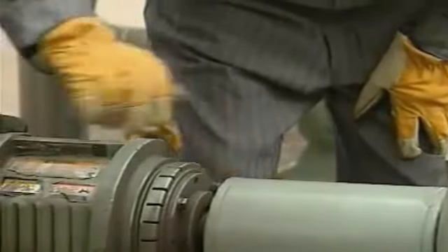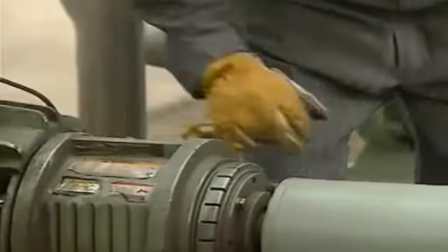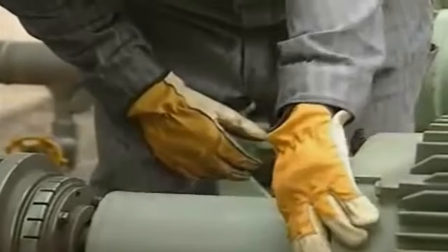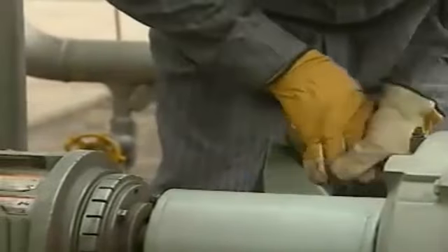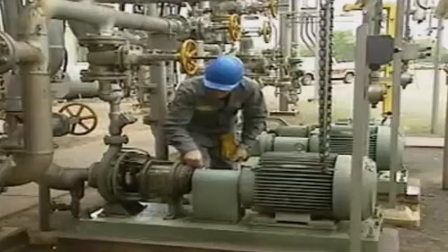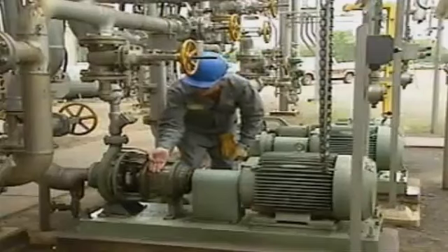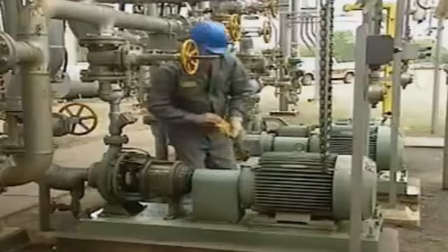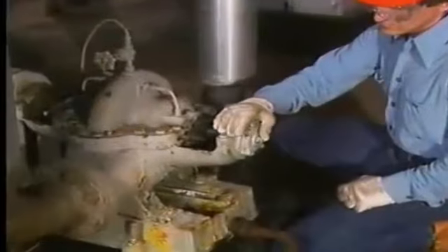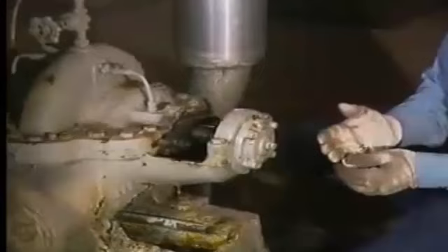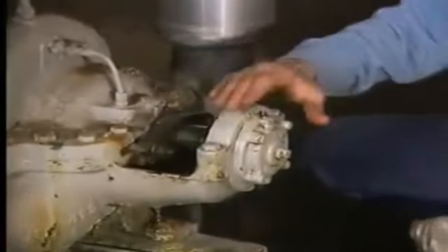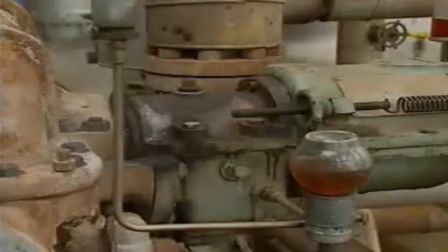Carefully touching a bearing housing is the simplest and most often used method of estimating the operating temperature of the bearing inside. With experience, a mechanic can tell by feeling a bearing housing whether the bearing is running too hot. Although the temperature of the bearing housing is not identical to the temperature of the bearing, the two are related. An increase in the temperature of the bearing causes an increase in the temperature of the bearing housing. An abrupt change in the temperature of the housing could indicate a problem with the bearing.